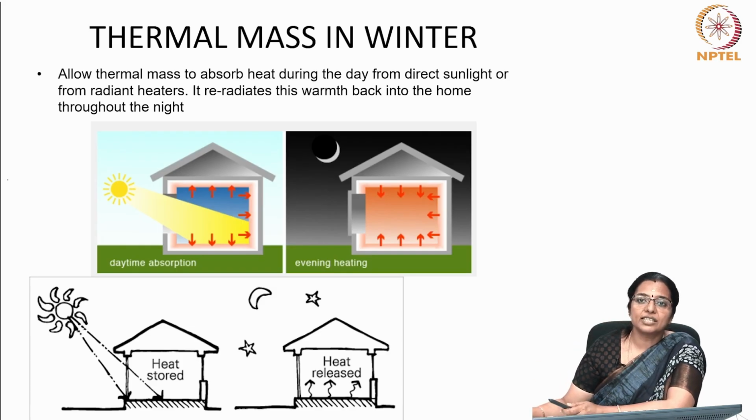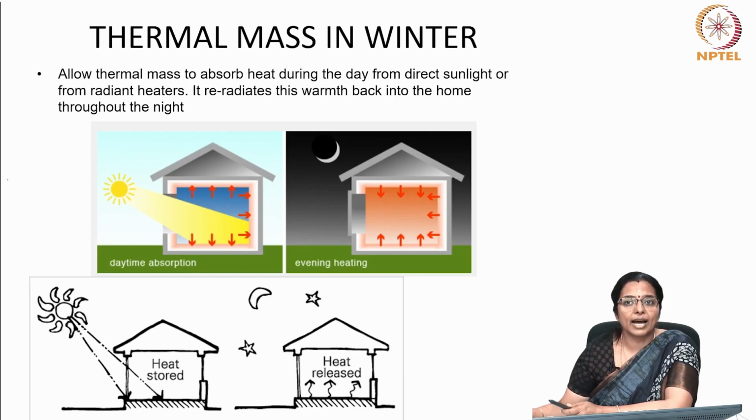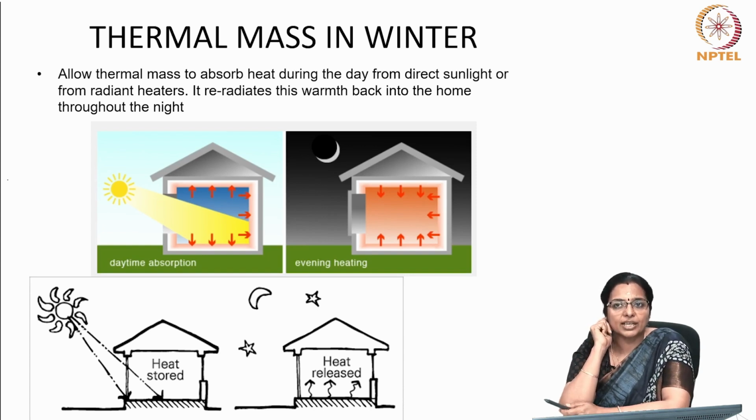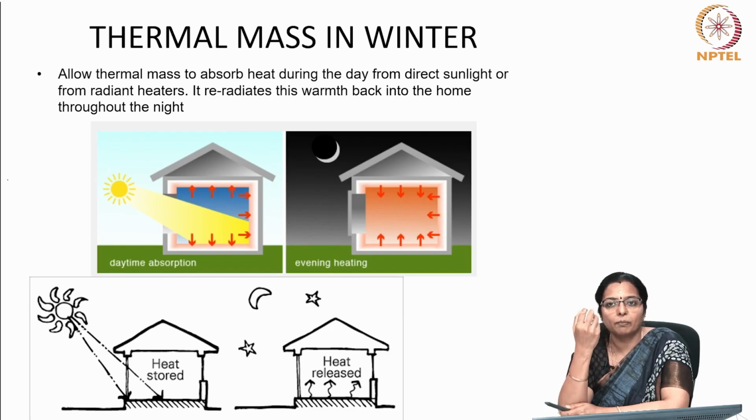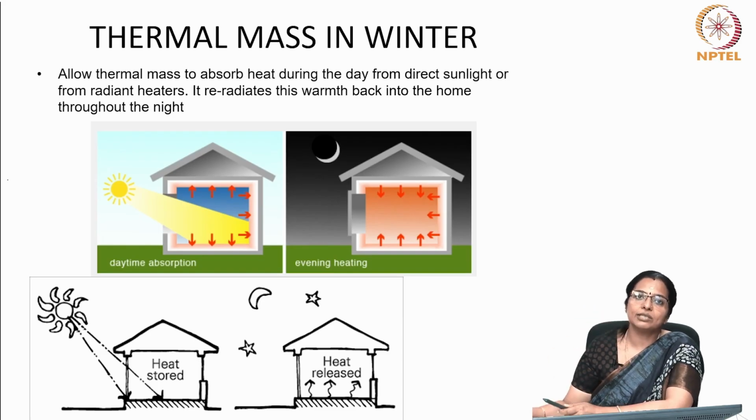Because thermal mass distinguishes itself as a tool for dampening of temperature amplitudes, it works best when excessive heat builds up and requires absorption and much later disposal. For example, where the excessive heat generated by solar gain is absorbed by the building fabric during daylight hours, or where a particular environment has excess heat generated by the people who stay inside, absorbed and emitted into a cooler nighttime space.